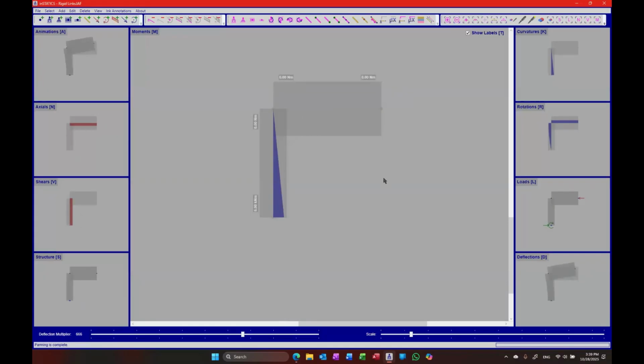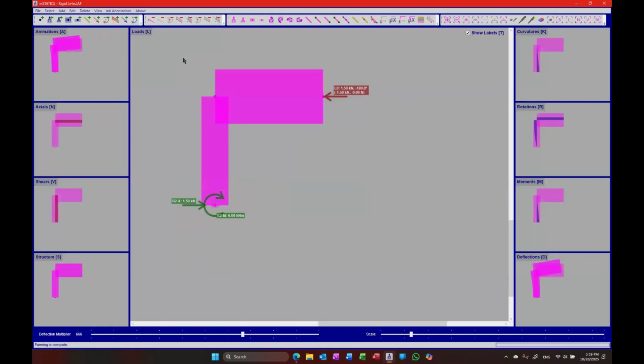But is this really what I want to simulate? Maybe not, because how are you going to get a concrete structure or connection like this, or a steel connection for that matter? You're not going to be able to connect two things like this in almost all cases. This element probably is going to be taller, and this element's going to be backed. So what would be the real behavior of this is the question.